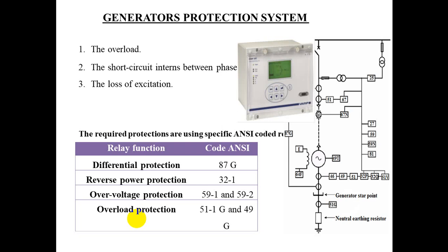To this end, provision is made on the larger machines for independent supplies of steam to be sent to certain points on the casing. It is desirable, therefore, to provide a means of measuring the actual expansion to assist the operator to feed the steam to the correct point and also to provide indication of any dangerous expansion.